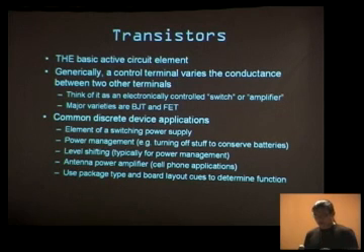There's a lot of varieties of transistors. It's not important for this talk to know what they are, but it's important to identify them, and know why you might see them on a motherboard. So even though your chip has a billion transistors in it, you still have discrete transistors on a motherboard. And when you see those, typically that's going to tip you off that you're looking at a switching power supply, or something for power management, something that will turn off stuff to conserve your batteries, or turn on stuff to add more computing power if you want. They're sometimes used for level shifting in power management circuits. If you're looking at cell phones, sometimes you use the amplifier for the output of a single discrete transistor.